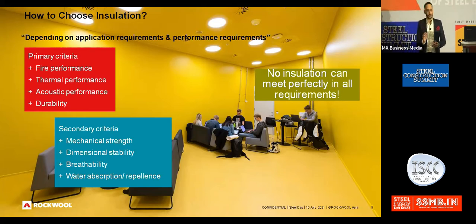There will be a possibility where you will get thermal performance and acoustic performance, but you will not get fire performance. There is a possibility of getting fire and acoustic and not the thermal performance as required. So if I compare, a generic glass wool would give you very good thermal performance and acoustic performance, but you'll have to check whether it is giving you the right fire performance or not. Same thing goes for a slag wool. Slag wool, because it is made out of metal, it may give you fire performance or acoustic performance, but we have to check whether it is giving you the right thermal performance, especially over a longer period of time or not.